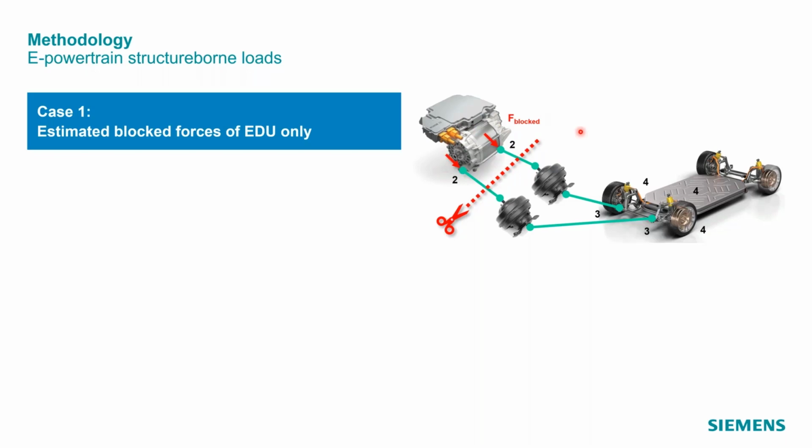If we know that this is where we want to obtain these blocked forces, the next question that we need to think about is what kind of coupling exists at this location. At this point, I will not make any assumptions yet. I will just say that for general applications, we shouldn't assume weak coupling exists. Weak coupling is a special case where you have a very significant mismatch in the impedance of the receiver and the source. So in general cases, we should assume strong coupling, and that means that we want to apply the in situ TPA method.